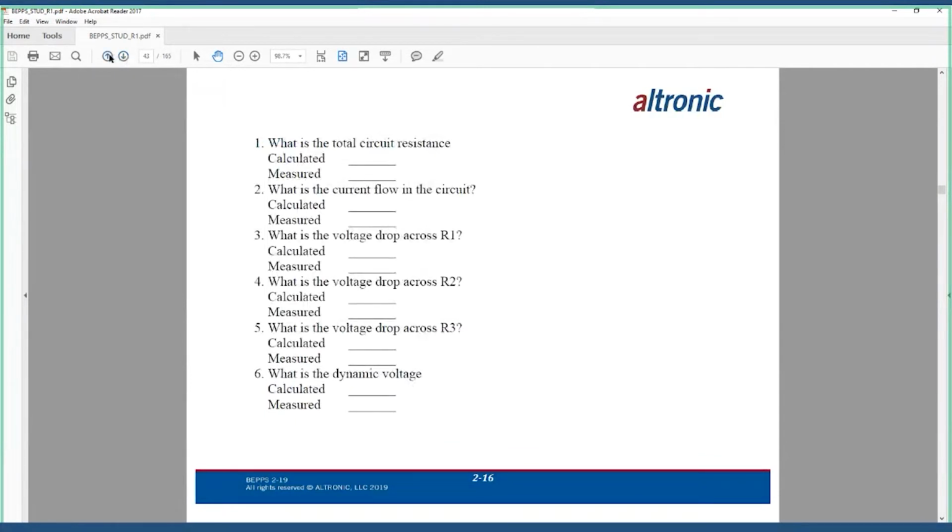Does anybody see the benefit of knowing this information? This would be good if you've got some kind of circuit set up and you've got problems, low voltage, and maybe you realize that you've got voltage drop in the line coming over to your circuit. It's not just the circuit. So if you add them all up and you can't find some voltage, maybe I need to put an ohm meter on this wiring run, and maybe I've got a burnt wire or something. That's one application I would think. For me personally, if I'm trying to figure out something about a voltage drop or a ground potential loop problem, something like that, very valuable.